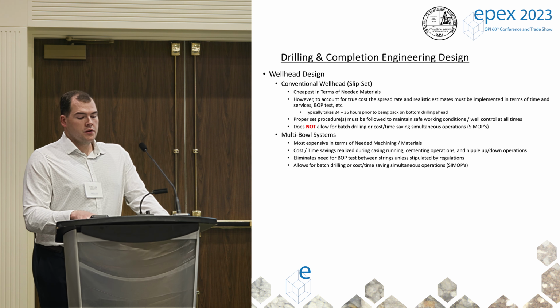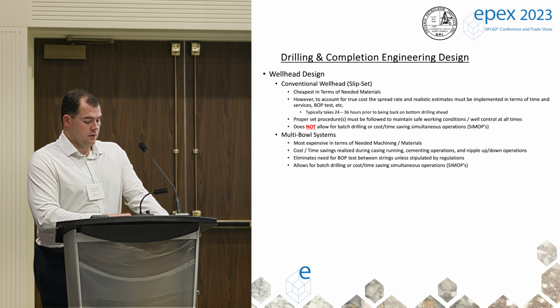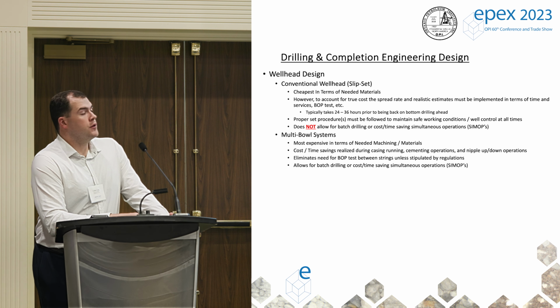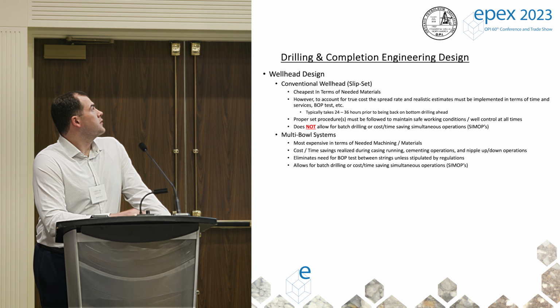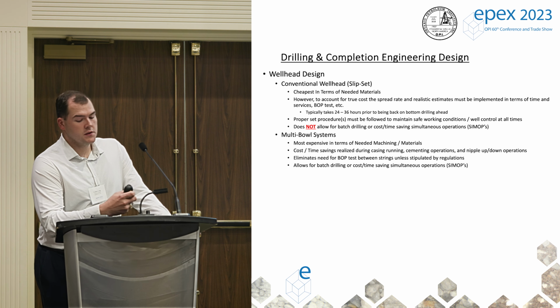For single-use wells or a one-off well, conventional slips are fine. Make sure your casing and wellhead program is set up to stay activated. Make sure you have an H plate on top. If you're going to do any type of batch drilling, one thing I'd recommend people really move to is multi-bowl systems. There's a lot of cost savings there. You don't have to break your stack anytime. You land your bowl on the different load shoulders, you go ahead and start running the hole you drill out, and you're waiting on cement after that point. I would say between a conventional slip set and a multi-bowl system, you're saving 24 to 36 hours per casing size.